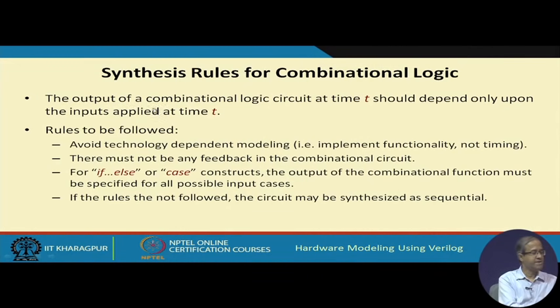There is no notion of clock or other kind of synchronization in combinational circuits. So, the output of a combinational circuit at some point in time, let us say t, should depend only upon the inputs applied at that time. Of course, there will be a delay of the circuit that we are not mentioning here.